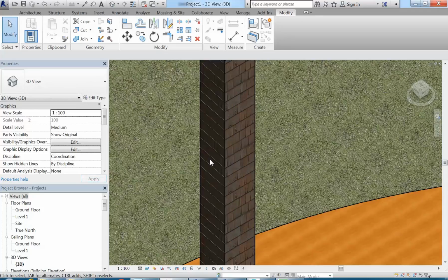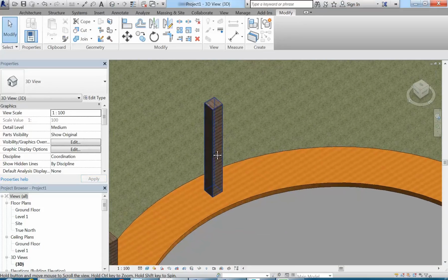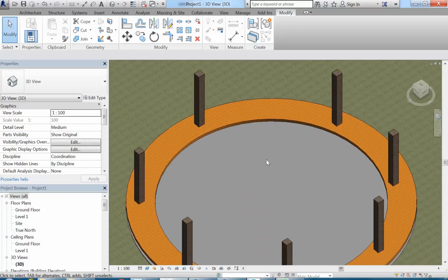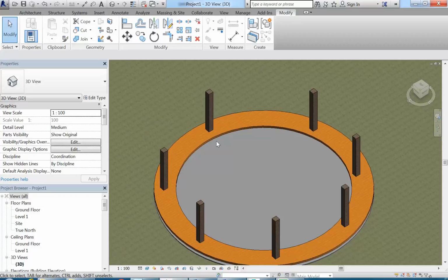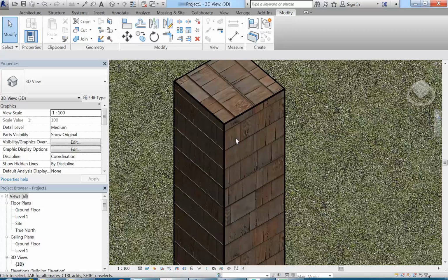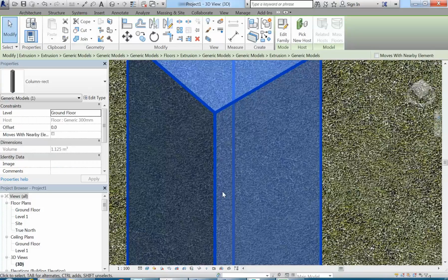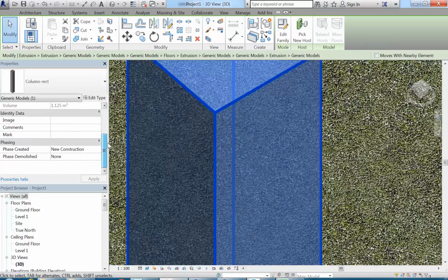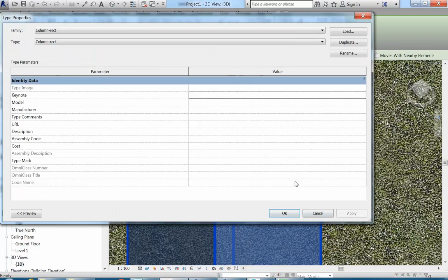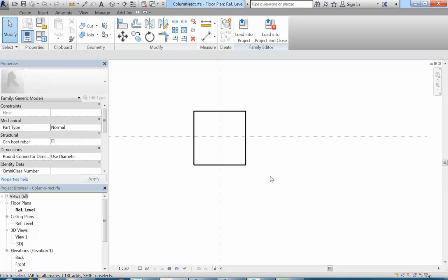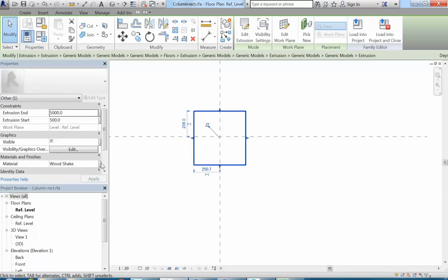So they've obviously changed, but now this is where things get a little bit more confusing. If I want to change that now, what would I have to do? If I want to change that material and use, say, a different texture, I don't like that pattern, I want to use a different image. Yeah. So I can't, there's no option there to change the material, and not in there either. Yep, we would exactly have to go to Edit Family, and then I can select this object, and there's the material.